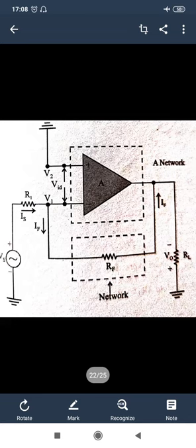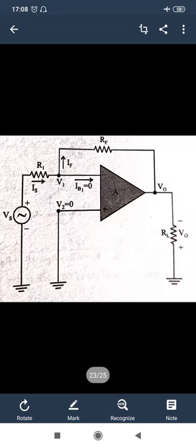It is a simplified way where we provide the input at the inverting terminal and the non-inverting terminal is grounded, and that is the shunt voltage terms which is provided at the input in shunt way. So it is more simplified where we use the inverting terminal providing the source Vs here and feedback V0 in shunt way with respect to Is and If, that is the parallel conditions of current. So Ib1 is equal to 0. So the inverting amplifier with feedback is the voltage shunt topology.